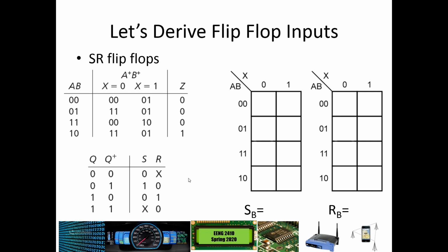And again we have our binary table and we have our logic for the SR flip-flop. We are going from B here. We have a 0 to a 0, that gives us 0x. We have a 1 to a 1, that gives us x0. We have a 1 to a 0, that gives us 0, 1. And we have a 0 to a 1, so that gives us a 1, 0.